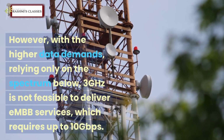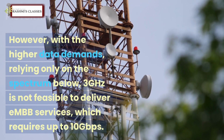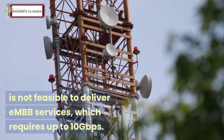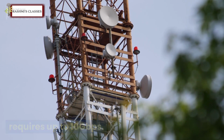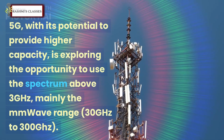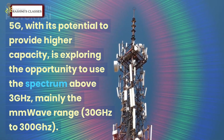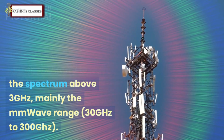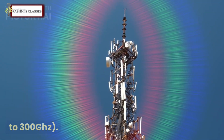However, with the higher data demands, relying only on the spectrum below 3 GHz is not feasible to deliver eMBB services, which require up to 10 gigabits per second. 5G, with its potential to provide higher capacity, is exploring the opportunity to use the spectrum above 3 GHz, mainly the mm wave range, 30 GHz to 300 GHz.